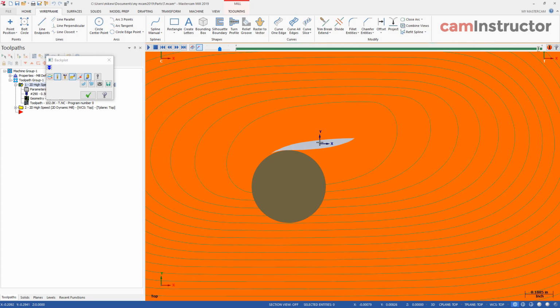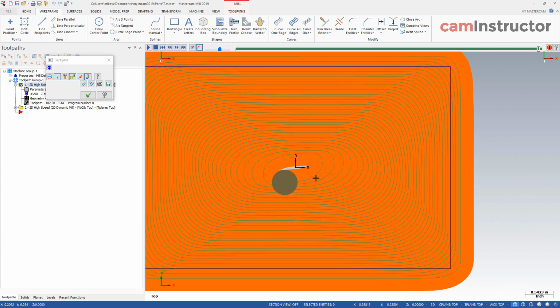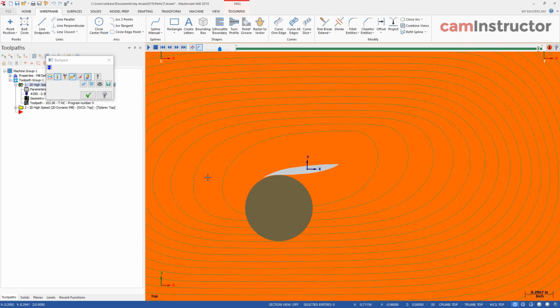What can happen is this can actually fold over. It can push away from the cut. The cutting pressure can be higher than how strong this material is to resist deformation. And if it does fold over, then your cutter could engage this whole piece that's been folded over at once. This piece could break off, and it could break your end mill. So you need to be cautious about what happens, not from the step over here, but from the actual material that's left over because of the cut.